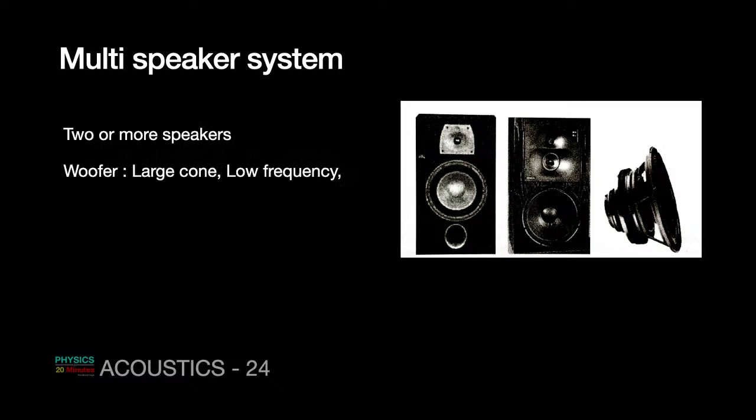In some of the advanced designs, you get three speakers here also. The woofer, this bigger one, has a large cone for low frequency. It has a large coil, a deeper cone and soft suspension. It's a very soft suspension, it moves very smoothly.